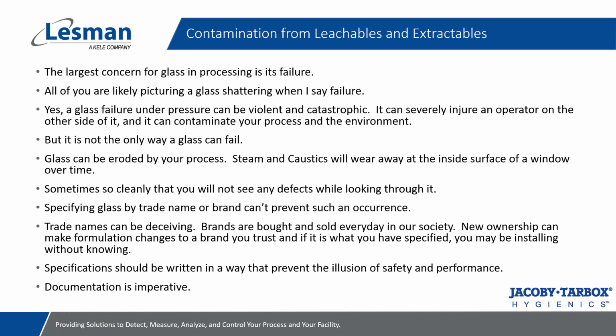So you have to make sure that you're using the right materials so that they can't be degraded by your process. The other thing that we run into oftentimes, and I spent a lot of time on it in a larger presentation specifically about this, is trade names and brands. It terrifies me when I see specifications from facilities that are written based on brand or trade name. And the reason for that is that brands and trade names can inherently be deceiving, and brands are bought and sold every day.